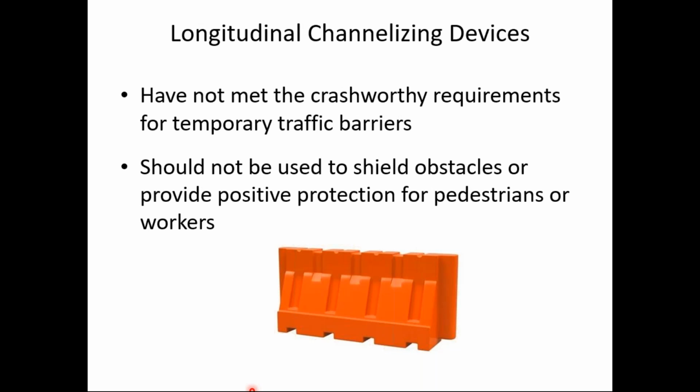Again, these are longitudinal pedestrian channelizing devices. And I want to emphasize again, these have not met the crash-worthy requirements for temporary traffic barriers. So if your traffic control plan or other requirements call for positive protection for pedestrians or workers, these are not the devices to use because these do not provide positive protection from intrusion by motor vehicles. These are not crash-worthy barriers.